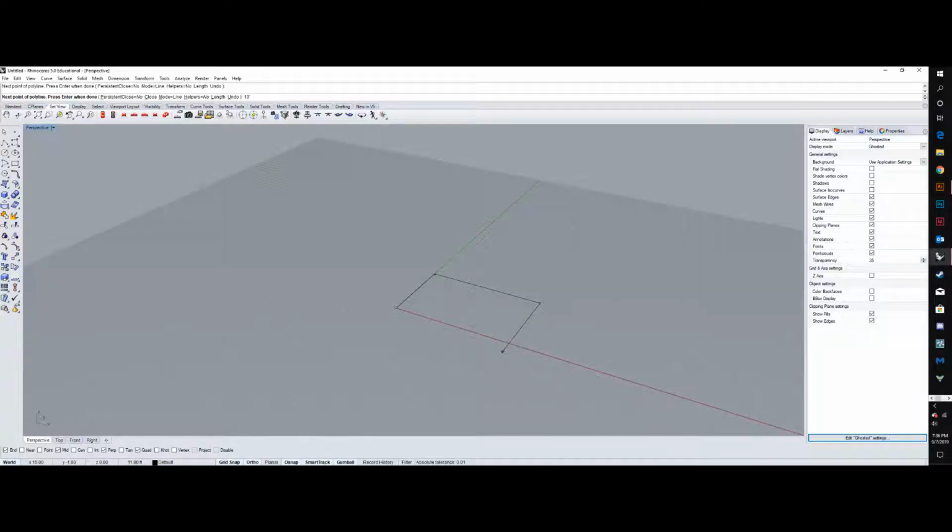And notice whenever I type this in, it's showing up on the command bar up there at the top, and I'm typing in feet with the little feet symbol instead of the inch symbol, which would look like this. We're going to switch that to feet, and then I'm going to click in the direction that I am applying that distance.